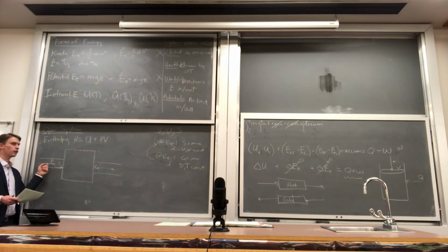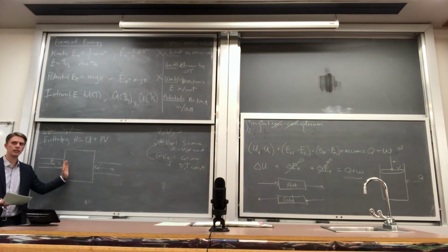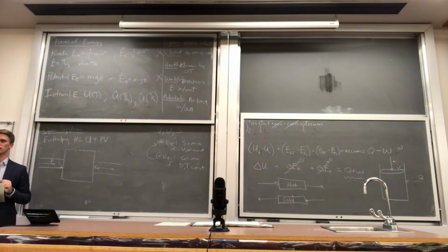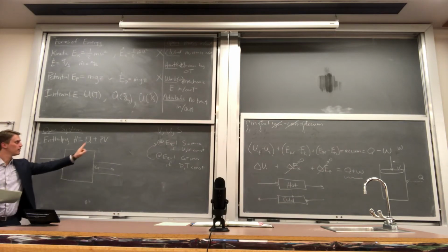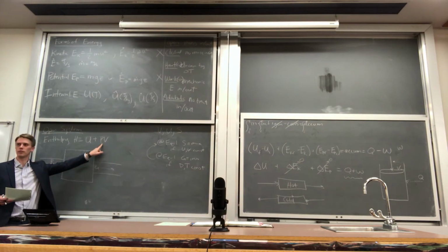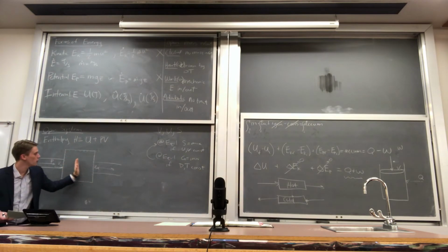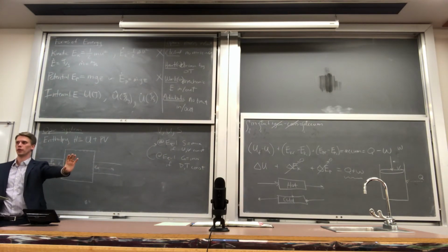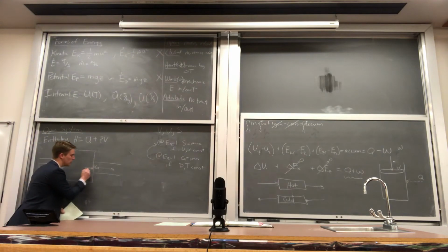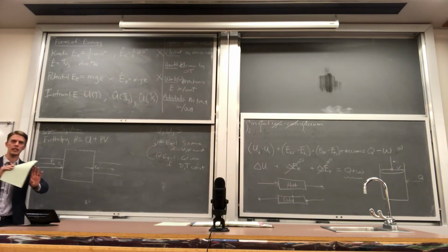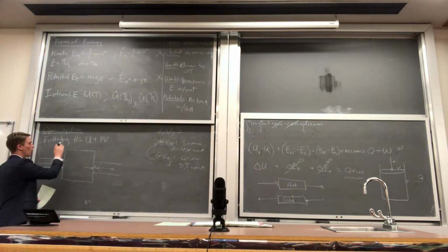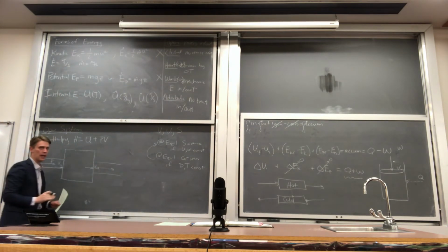So not only is the fluid bringing with it the energy stored in its molecular state, it's also physically pressurizing the system a little bit. That's what this PV is. Likewise, when it flows out, the system has to push out that fluid by physically squeezing it out of the system. So that's why for open systems, we always use enthalpy.